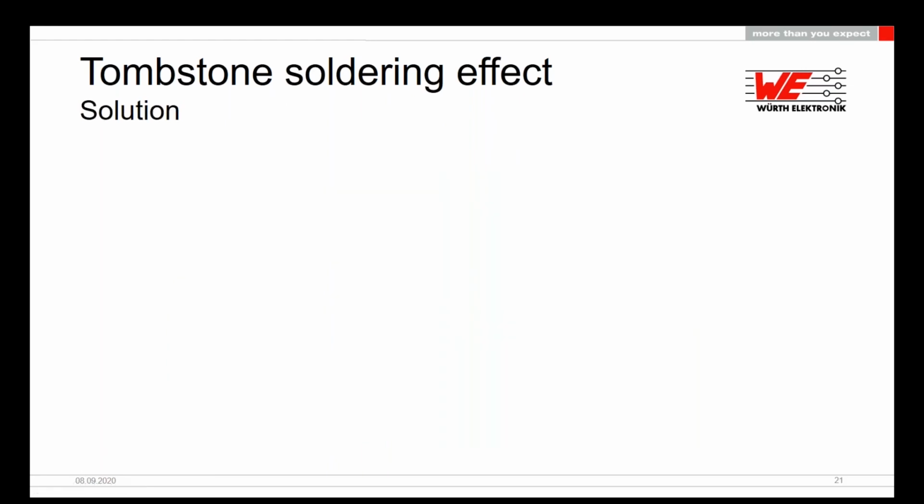As shown in the last two pages, the time difference of the solder paste wetting is the main cause of tombstoning. To avoid this problem, please check first your solder paste. The solder paste should not be too dry, and we recommend the thickness of 120 micrometers, not thinner, and please apply it evenly on the land pattern.